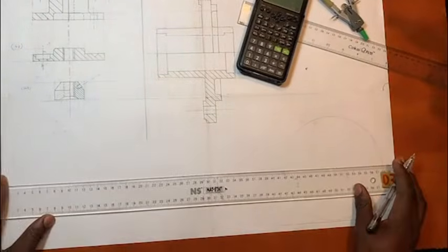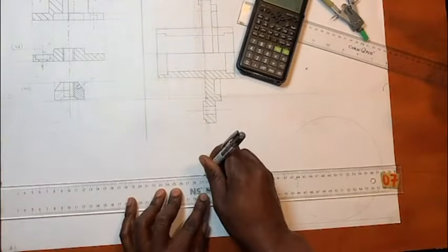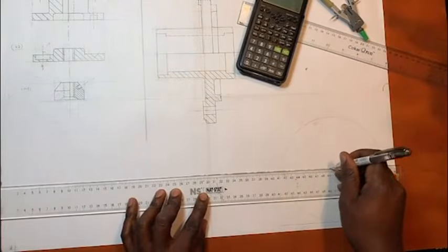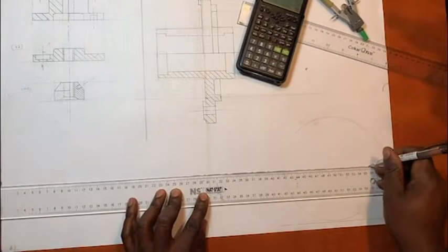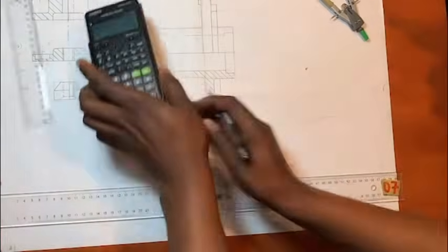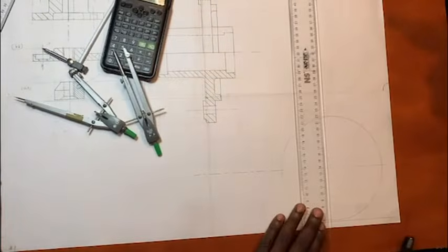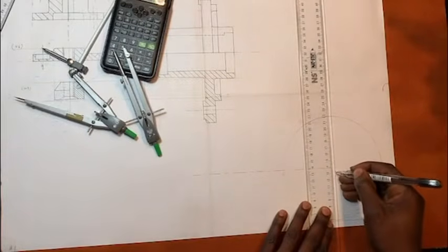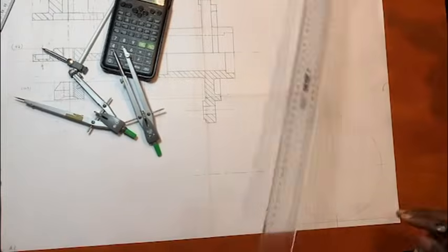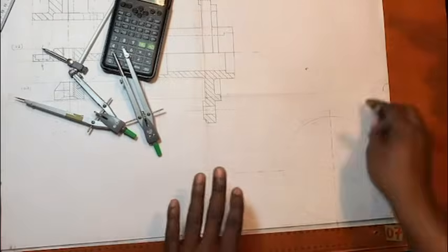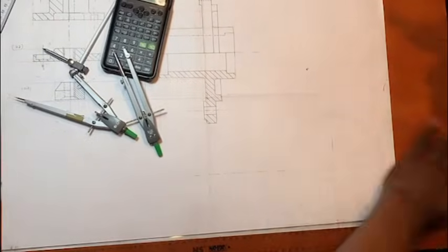Then from there, you can have a left view. This is the left, and you can have a horizontal center line. I just mark here, here I place my drawing compass, and now I draw the vertical center. Okay, so this is going to be the biggest dimension. I'm not going to have another one that is above this.